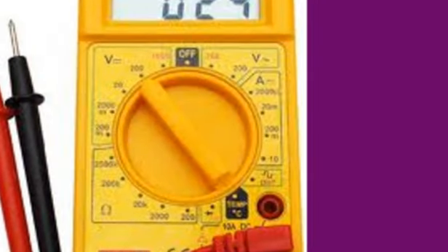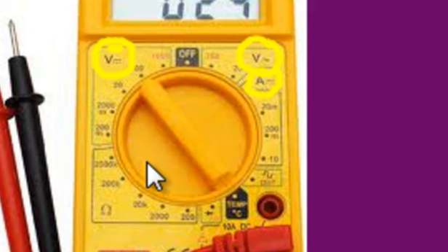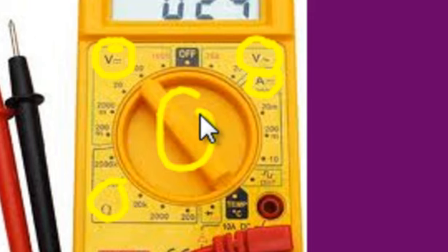If you look at the dial, you see that there's a section there for voltage, and actually two types of voltage. There's a DC voltage, for like a battery. Let me get to the right pen here. So here's a DC voltage. It's kind of like a straight line. And then this is AC voltage, which you're not going to use. And right underneath is amps, and then over here is ohms. So depending on where we turn this dial, we can measure each of those three quantities.